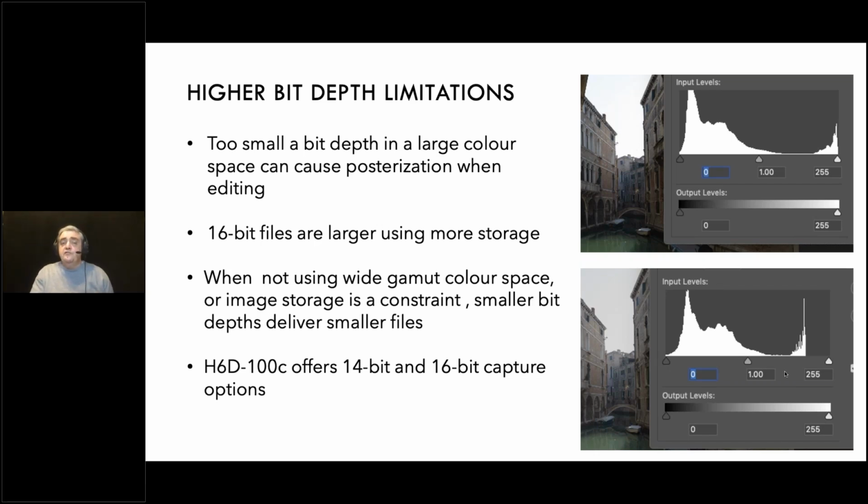And we then transform that data and, should we say, remap the values from the sensor into a full 16-bit color definition for the tones. And in certain cases, we actually transform values so that they would be outside of a 14-bit definition, so that it's actually a proper 16-bit value.